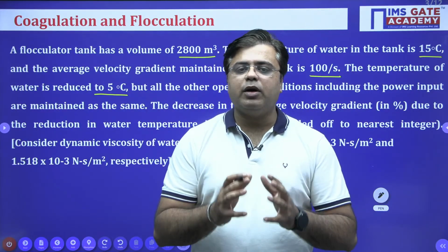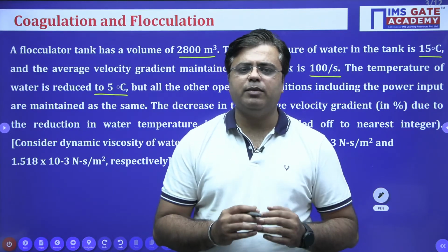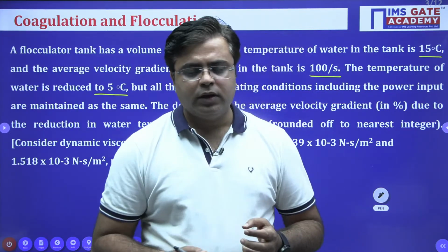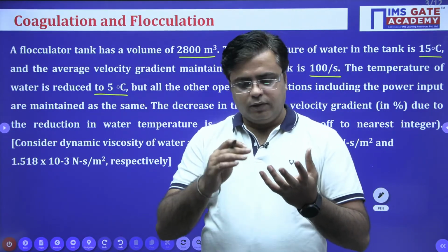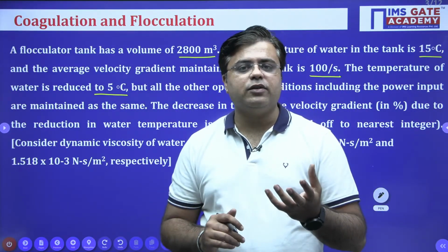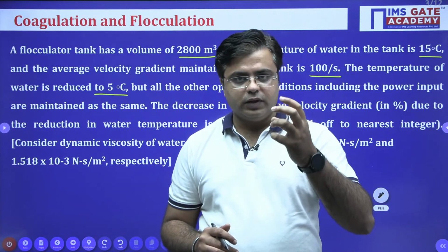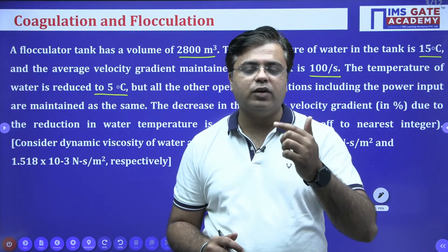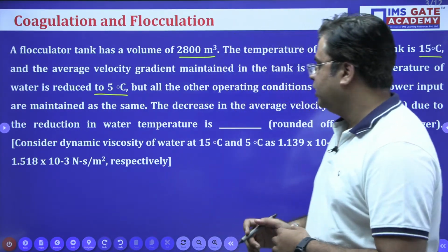For the same amount of power given to this water, the intensity of mixing will be less. When you reduce the temperature, the resistance offered by this water will increase. Dynamic viscosity will increase.